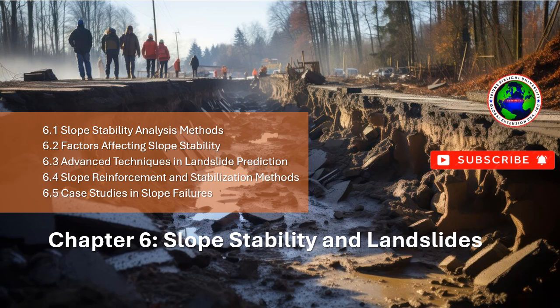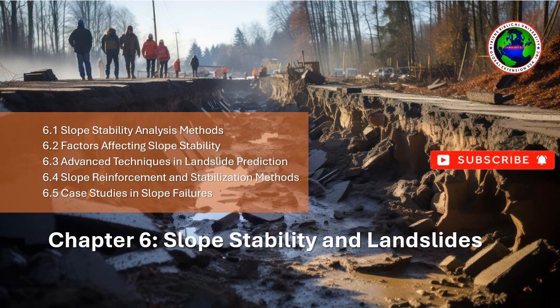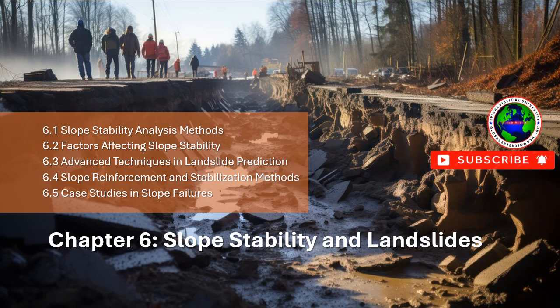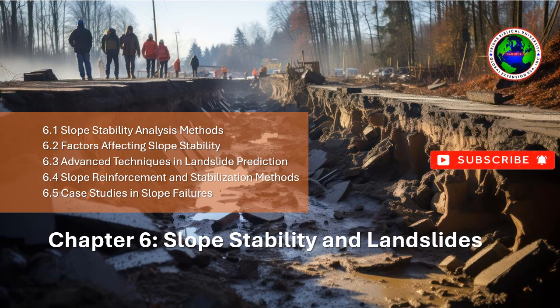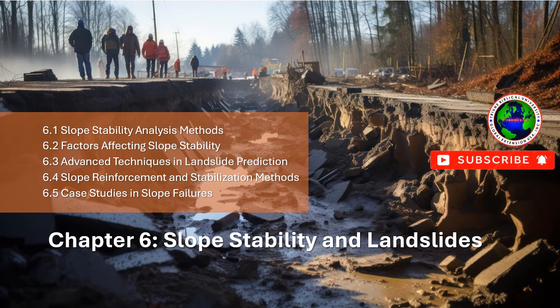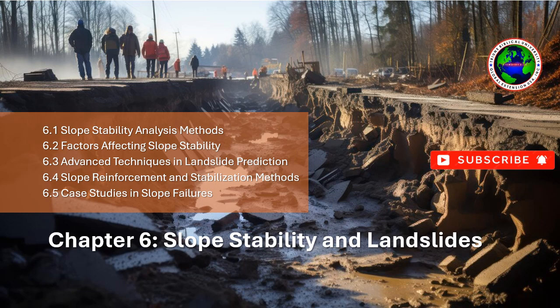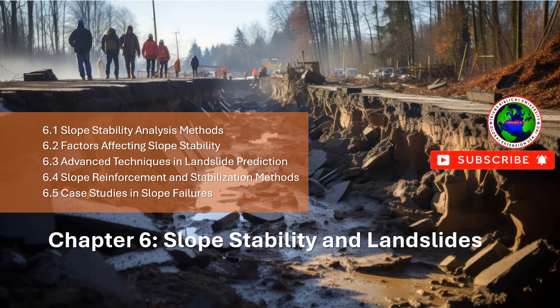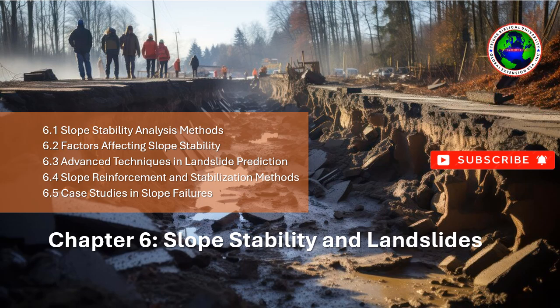Chemical grouts, such as sodium silicate or polyurethane, are used in situations where water flow needs to be stopped or where the soil needs to be solidified without altering its texture significantly. Compaction grouting. A thick grout mixture is injected into the soil to compact loose materials and increase density. This technique is particularly useful in areas with soft soils or loose sands.